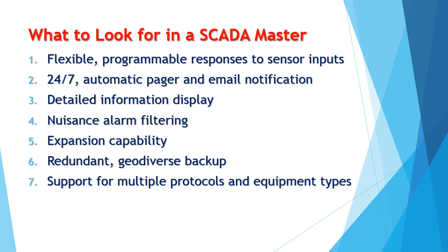Next, redundant geodiverse backup. The best SCADA systems support multiple backup masters in separate locations. If the primary SCADA master fails, a second master on the network automatically takes over. It should be done with no interruption of monitoring and control functions.